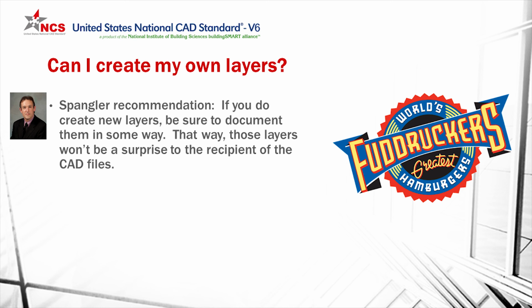Now, one recommendation I do have, if you do have to create new layers, be sure to document them in some way. That way, those layers won't be a surprise to the recipient of whoever gets your CAD files. So let's say someone has given you a project and in the contract language it says, I want you to follow the National CAD Standard. And when you're developing these drawings, you realize, oh, I need a layer for a particular item that's not covered in the National CAD Standard. So you would create a major group or a minor group and then put that in your drawing.